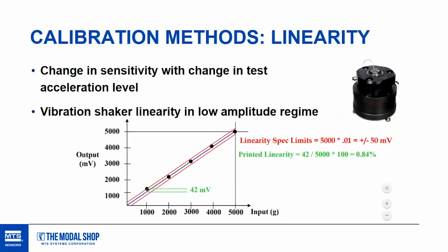The simplest way is just keep that sensor on the shaker and do step sine tests, but instead of changing the frequency with each of those sine waves, change the test amplitude with those sine waves. And up to a certain level, not pictured on this plot here, it's going to be way down around 40 Gs, 40 Gs. That's about the highest that we can test on the air-bearing shaker. It's a limitation of the continuous nature of the test.